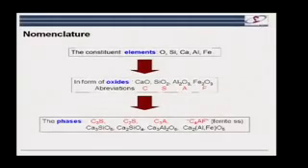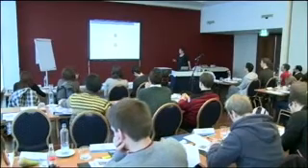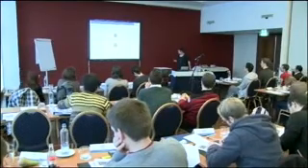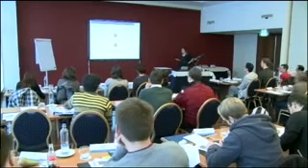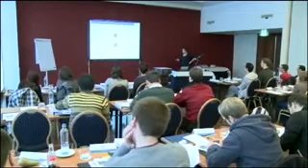First of all, we have C3S. This is the most important. Tricalcium silicate typically makes up between 50 and 70% of the final cement. Then we have the aluminate phase, C3A, and we have the ferrite phase.